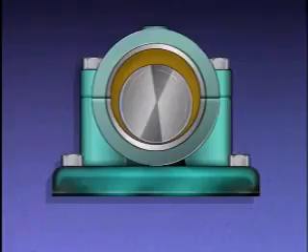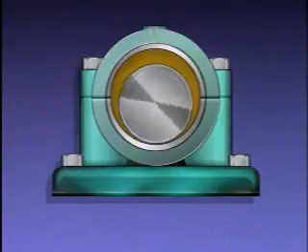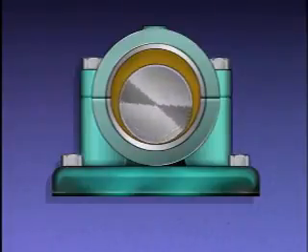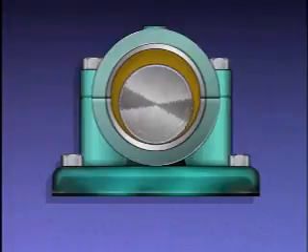There is metal-to-metal contact between the bearing and the shaft journal at the bottom of the bearing. Most of the oil has been squeezed out from under the journal by the weight of the shaft. This gap is shown much larger than it really is, so you can better see how the bearing works. As the shaft begins to spin, it pulls oil underneath the journal. The oil forms a lubricating film that partially separates the metal surfaces.